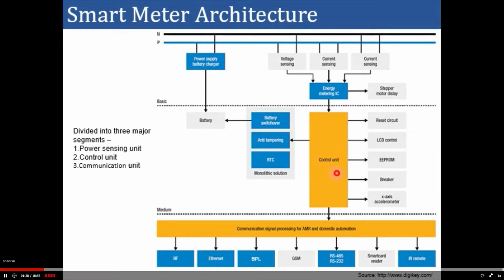This control unit will also derive a lot of quantities. Say for example, using voltage and current, it can derive the real and reactive power consumption and show it in the display. Now after all this information is processed, you might need to send it to a remote server.